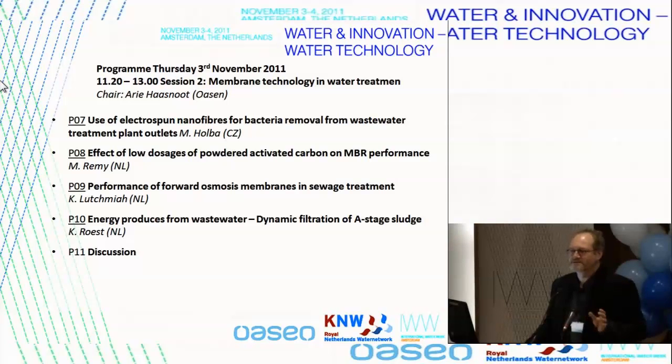It's a technique that I would say was discovered in the United Kingdom a couple of years ago, called ice pigging. So you use ice slurry to clean up pipe systems, which can be a distribution system for drinking water. And we tested it with Vitens company and Oasen company in some pilot project last year. And this year we applied it to a full-scale distribution system, and it really seems very promising. So I invite you to come and have a look and discuss the possibilities with us.